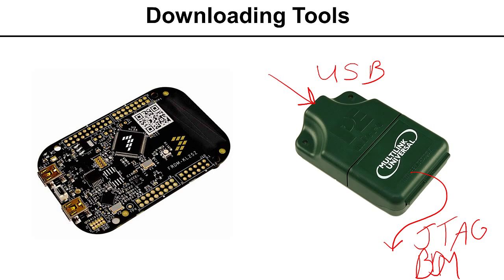Now, I showed you on the left, this is actually the Freescale, abbreviated FRDM, Freedom Board. Like most dev boards you get, whether from Freescale, Microchip, Renesas, or TI, they'll sell you low-cost dev boards that give you the microprocessor, but they'll integrate logic that has the debugger.